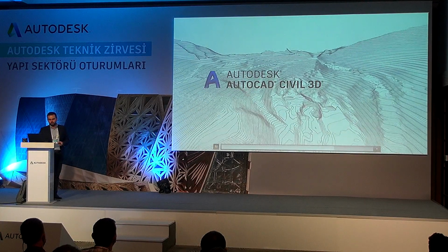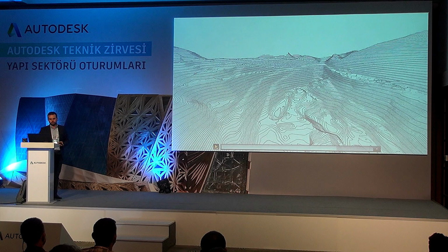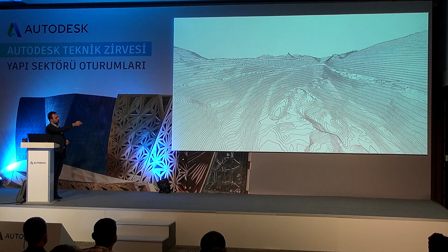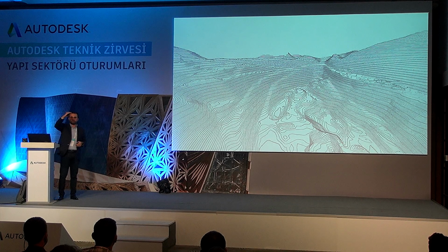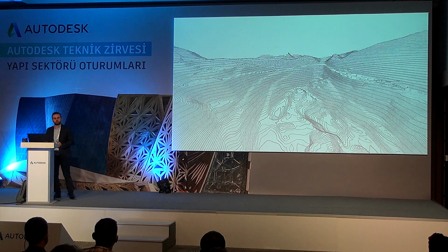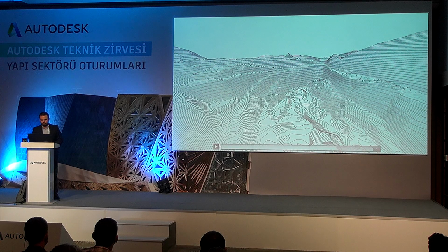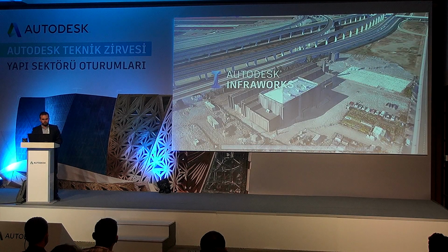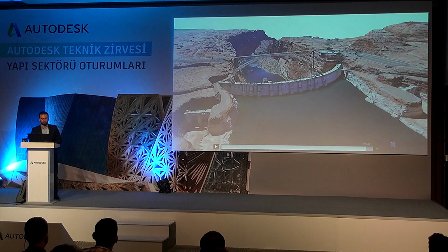So this is, for example, a case study or a project where a quarry site, a site where the excavated material was taken, using the drone, and every week the contractor used to fly the drone, capture the data, create a surface, and compare week 1 to week 2, surface 2 minus surface 1, and week 3 from surface 2, to check what is the progress on site. And definitely we can bring the same model into InfraWorks or even Revit or AutoCAD.